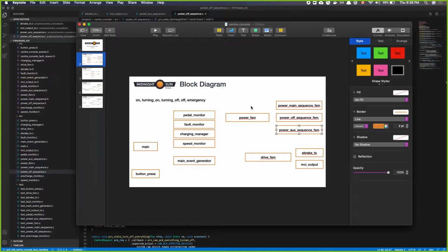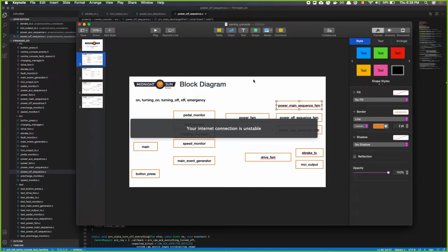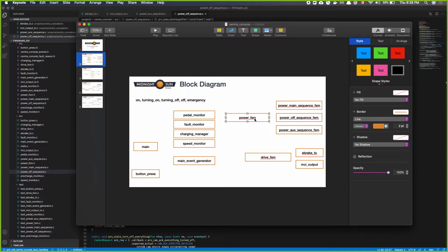Well, how do we recover from this fault? We just want to let the driver know that something like this happened, in which case we just broadcast a message. Then, for clearing that fault, the sequence goes back to its initial state, and Power FSM remains in the last state that it was previously at, because that transition didn't fully occur, right?